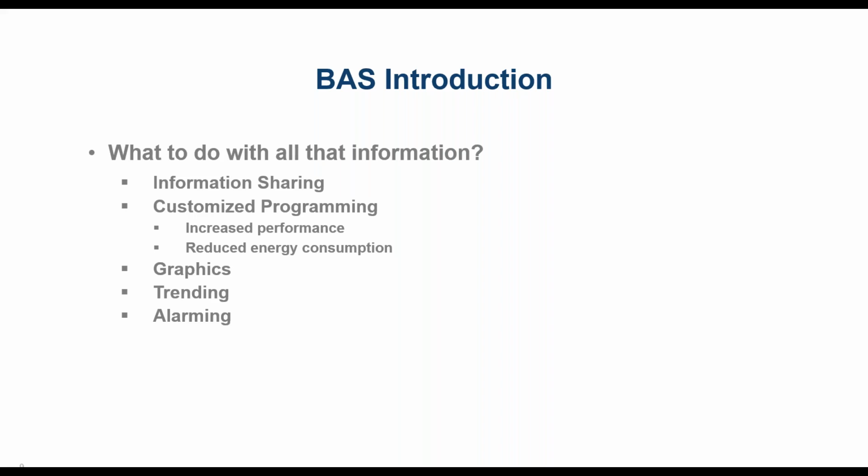We're going to talk about how to use graphics, which are displaying real-time information about how the system is currently operating, to greater benefit, essentially to help troubleshoot when issues arise. Having all that information in real time is great, but also being able to log all that information on set intervals, maybe every 5, 10, or 15 minutes, is what we call trending.